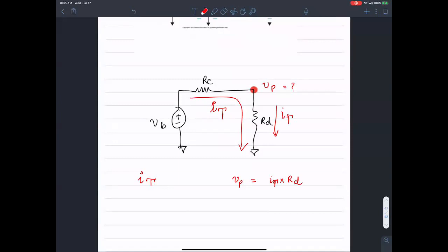So we just go right back to Ohm's law, but then we still have to find I total. How do you find I total? Well, we'd sum the resistors, and then take the given voltage, and then we would have the two other components of Ohm's law that we need to find the current. That's what I would generally do.